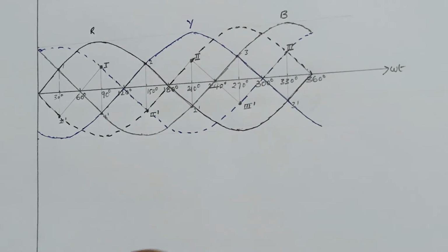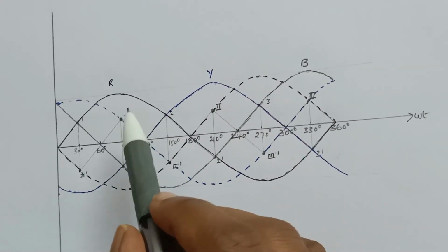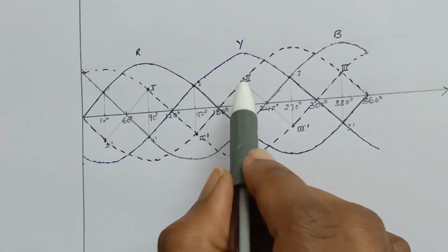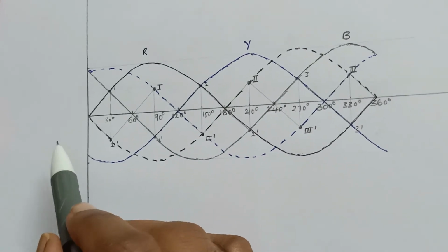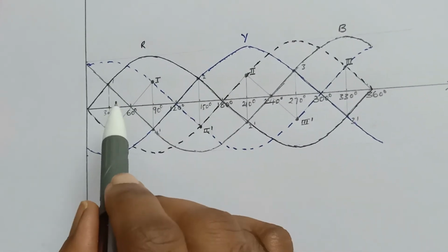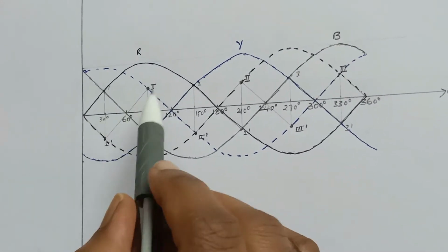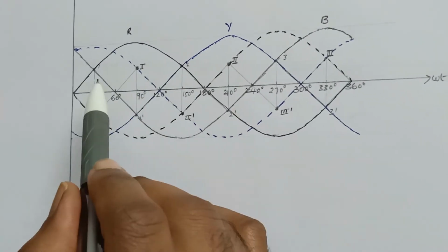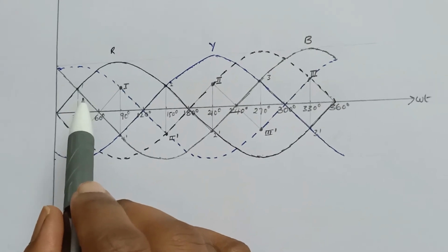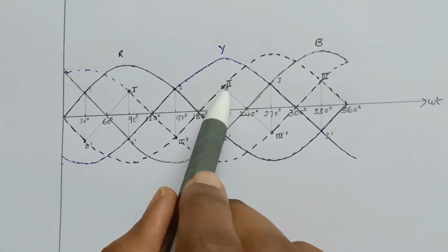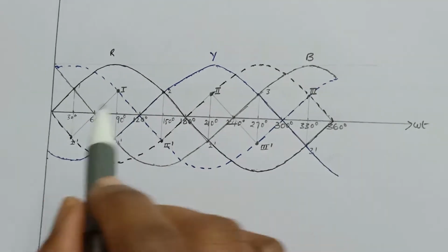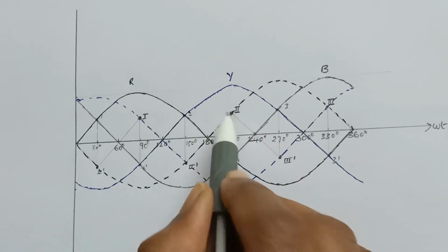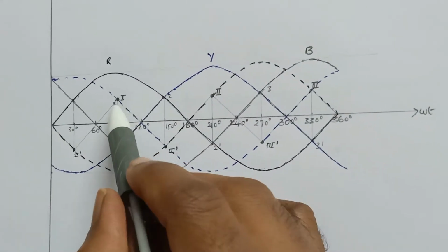Now let us concentrate on the tops of the positive group triangles, in particular the tops of the first and second positive group triangles. As we have represented their tops, it is easy for us to now identify. If these notations are not available, or if we have not marked them, then definitely we may get confused. Hence, it is recommended to definitely mark this representation. Okay. Now the tops of the first and second positive group triangles are this and this. Now through a smooth sinusoid join these two tops.